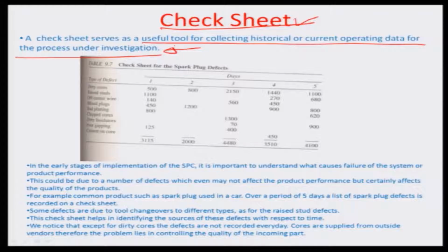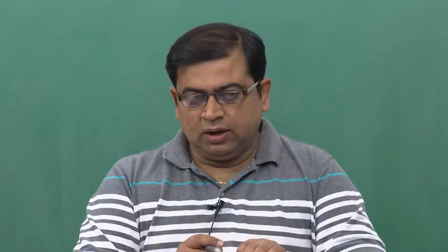This is recorded in terms of the chassis number and the engine number, and it is retained for almost one lifetime of the vehicle, so that if there is some warranty failure issue which comes up, you can refer to this check sheet and see if a repair was done on the particular vehicle, or even, to an extent, use that data towards recalling vehicles which may have potential problems from a certain batch of component being fitted.